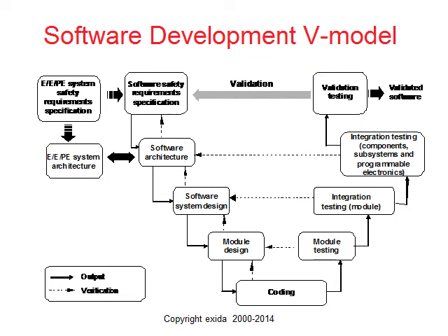Not that the hardware is not very important, but the software is also important, because that's often somewhat overlooked. A good percentage of the systematic faults are going to be introduced in the software development and design process or the implementation. So the requirements for the software process are very robust in IEC 61508. They're spelled out, specific steps, specific amounts of rigor that must be done. So that V model development process is very important.